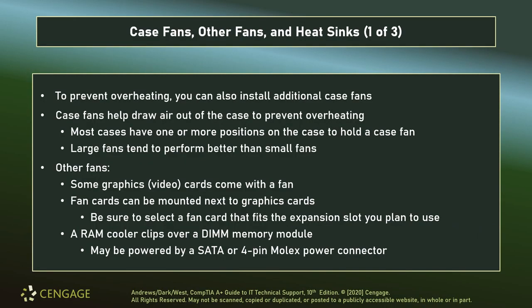Now, to prevent overheating, those additional case fans are good, but we have to make sure that they're flowing in the correct direction. Large fans tend to perform better than small fans. They tend to be measured a lot of time in what's called CFM, cubic feet per minute, and it depends on whether or not you're using fans that are insulated, you know, if they have grommets that help to rubberize the corners and keep them from vibrating, or if they have a very strong capacitor that allows them to spin at a higher RPM, that sort of thing.